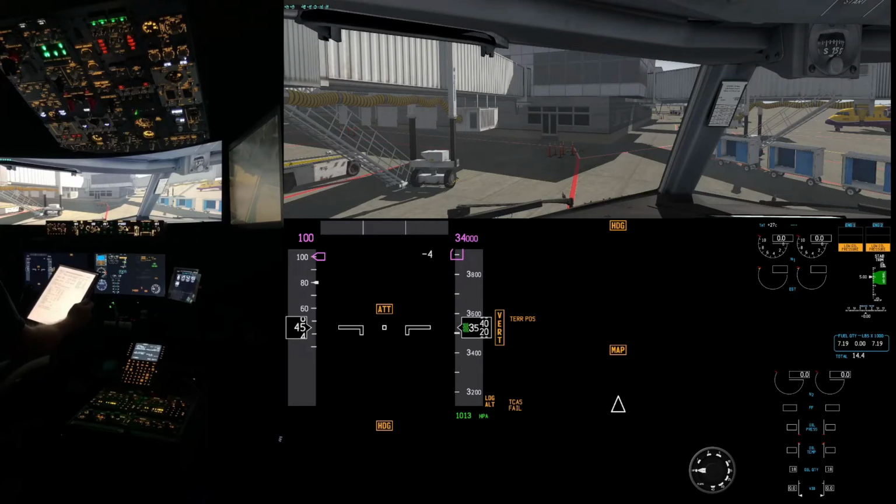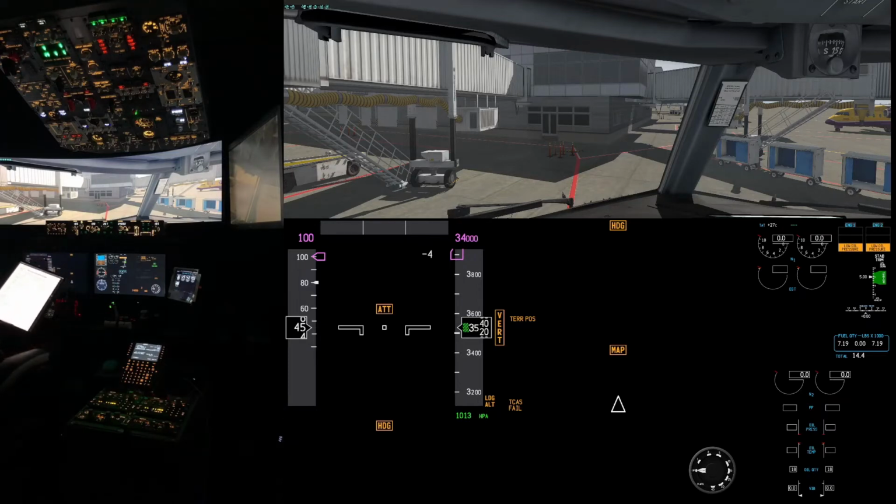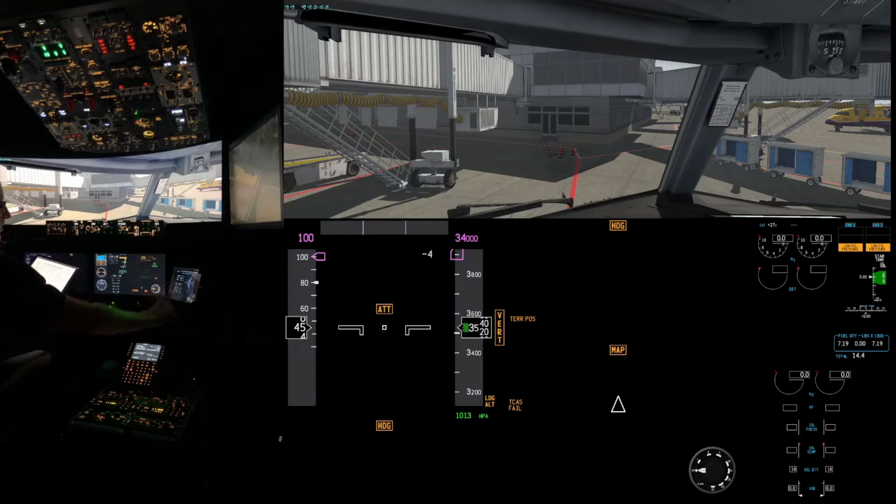So what we're interested in on this flight plan is the fuel and the weather and various other pieces of information that this flight plan will give us. So today we're in Calgary, we're going to be flying to Vancouver, so the flight plan has already calculated how much block fuel that I need. So it's saying I need 14.7 thousand pounds of fuel, so that's 14,700 pounds of fuel, which I don't quite have in the fuel tanks right now, so I'm actually going to type that number.